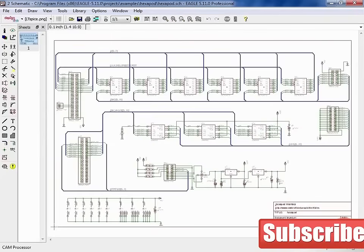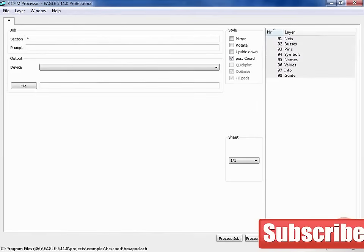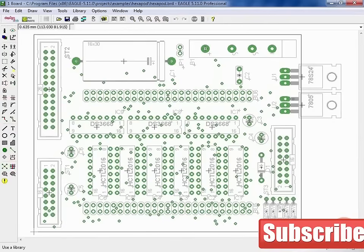We click on this button to generate the manufacturing data for a board, and we run the project with the rules that we place into the project. So as you can see, Eagle is a little more complex, but it is much more comprehensive. The Hexapod project fits into the dimensions of the light version of Eagle, which is available for free download for non-commercial use. So as you can see, we can do fairly complex things with Eagle, and it's a great piece of software for those serious about making professional quality circuit boards.